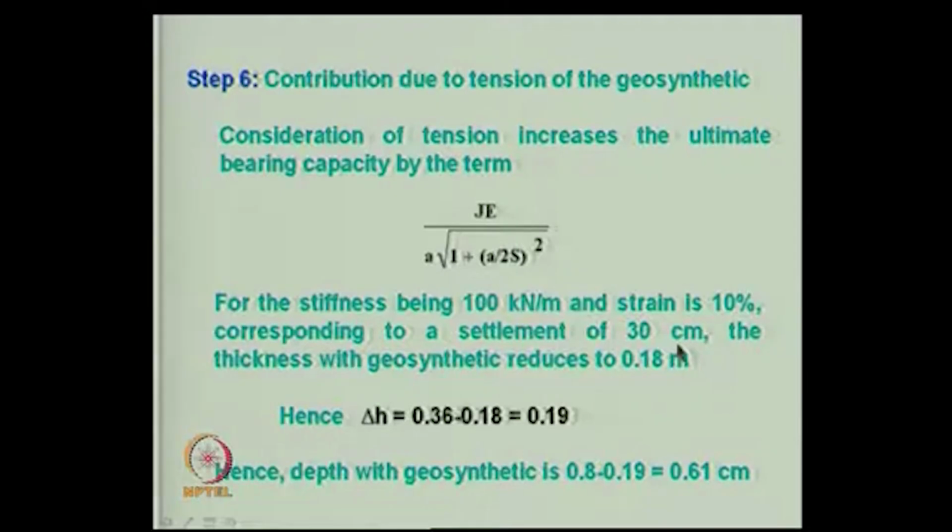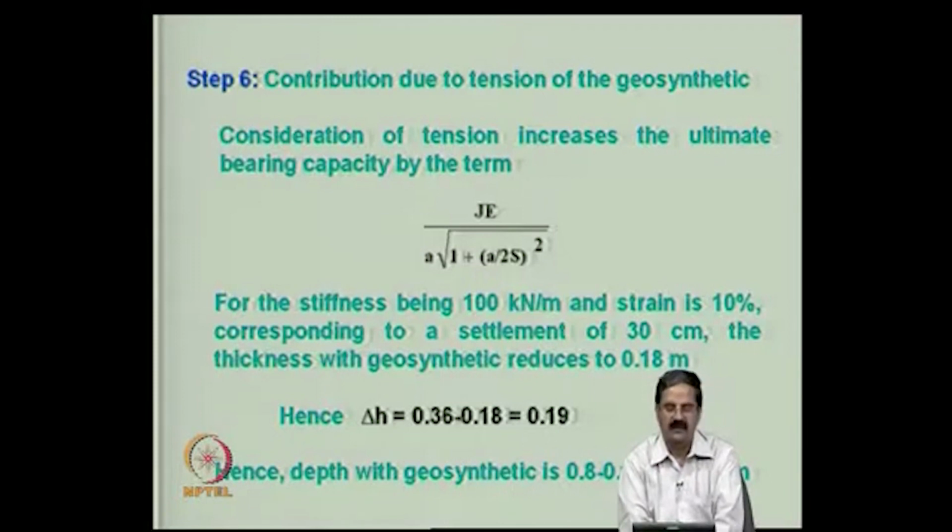So, if you consider the geosynthetic material stiffness on the reinforcement, there is a marginal difference, but the separation alone is good enough, particularly if you are trying to do a village road. You can just put a separator, nothing else. Separator is much cheaper, whereas the reinforcement is somewhat expensive. Consider that it is maybe 3 units just as a separator, but it can be 4 or 5 or 6 units if you want a good reduction in settlements and all that.